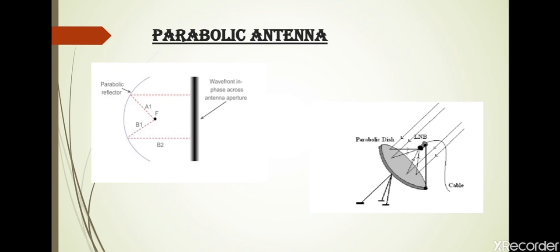The operating principle of parabolic antenna is that a point source of radio wave at the focus point F will be reflected into the plane beam along the axis of reflector. Conversely, an incoming plane wave parallel to the axis will be focused at the focal point. When electromagnetic wave hits the shape of parabola, the wave gets reflected onto the feed point. It receives the signal, converts it into electrical signal and forwards it to receiver circuitry.